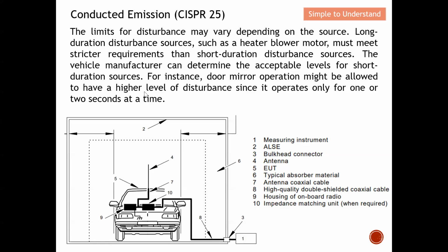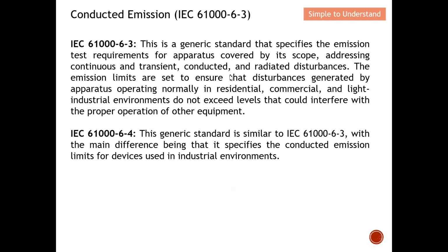So in short, for the vehicle standard, those that need to be utilized for a long time, for example aircon or heater blower, need to be stricter. For those that only run for 1 or 2 seconds, as this slide mentioned, like a door mirror, we can be a little bit relaxed on this criteria. Now let me quickly explain IEC